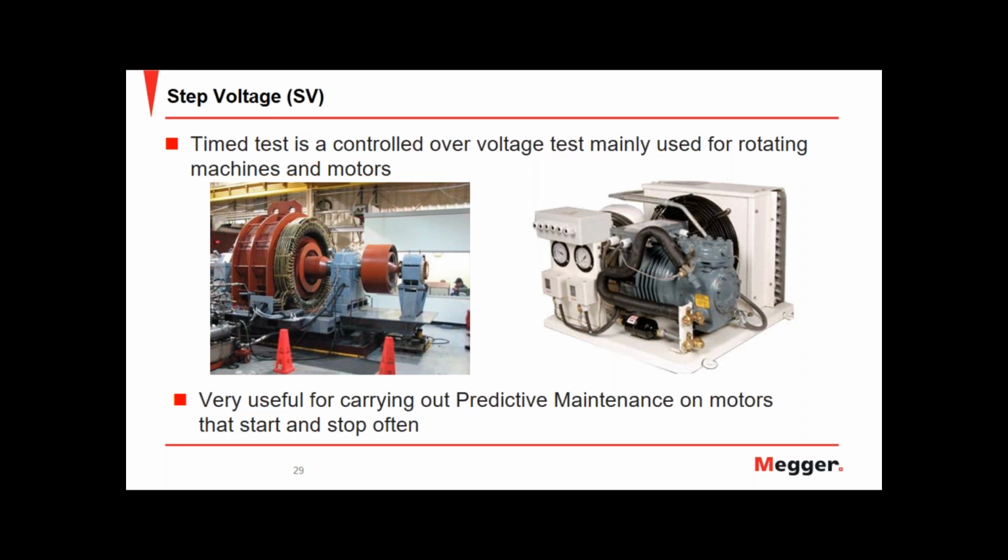It's very useful for carrying out predictive maintenance on motors that stop and start often. So they get exposed to greater starting currents and voltages, so the step test is very good for them.